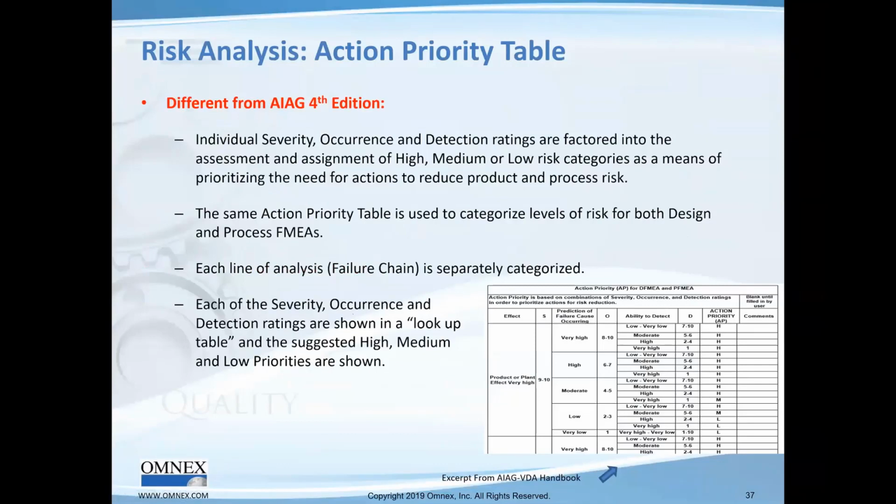All right. I hope you don't mind me taking a quick clip through here. That way, I'll get a few minutes to take Q&A. And so let's look at the action priority table. The action priority table is driven really by severity. Severity is the boss here that drives looking at occurrence and detection. And you actually get tables with red, yellow, three different colors in terms of high risk and lower risk.